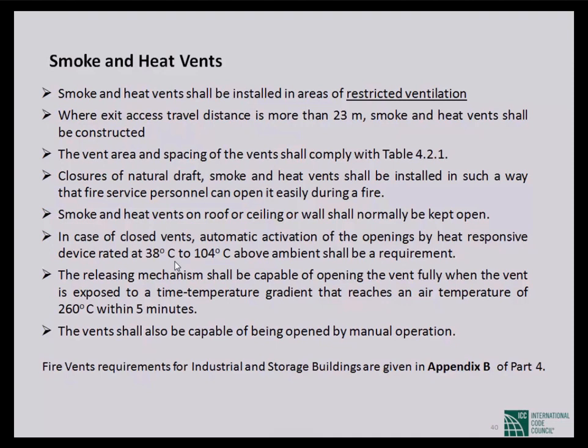Whenever there is fire, smoke will move from one room to another. If the building is not properly designed, the smoke will go to the stair. So you have to restrict this smoke propagation, and not only restrict it, you have to allow the smoke to go out. So you need some vent so that smoke can go out.